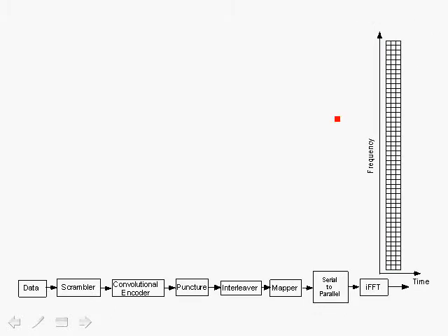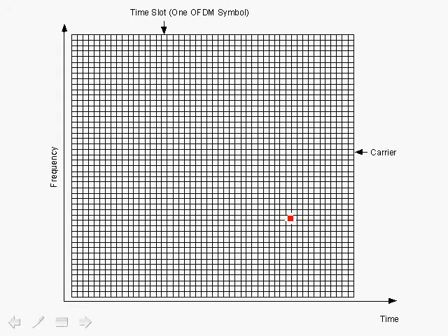Now, as more data is generated, again we assemble the data into 64 carriers, including all the nodes, pilots, etc., but focusing on the data carriers, perform an inverse FFT, and we get another symbol. We're showing the carriers and time, where time is showing OFDM symbols, which we refer to as a slot. Now, if we continue this process over a given number of time slots, where each time slot is an OFDM symbol, we will obtain a grid, as shown over here.